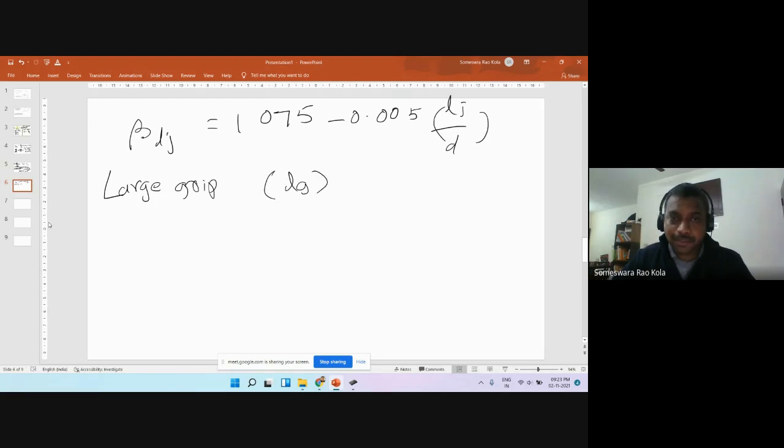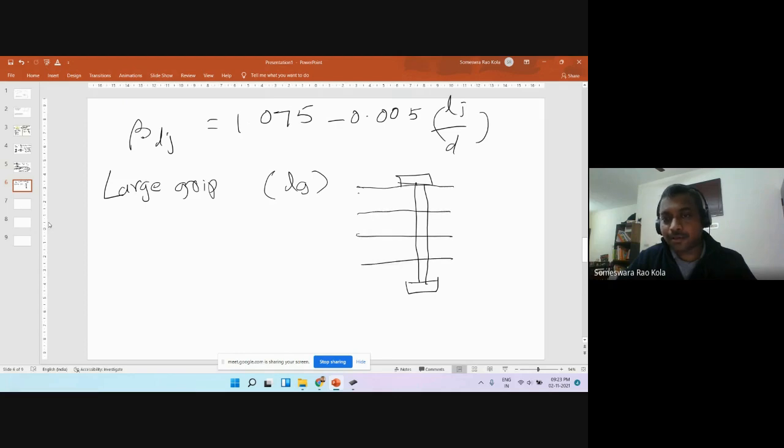So what you are trying to say is that, let's say your bolt is too long. For some reason, you are connecting a very large quantity of packing, or the connecting materials are too thick. So this bolt has a long length. Obviously, when you have such a long bolt, its strength is not going to be as effective compared to a short one.